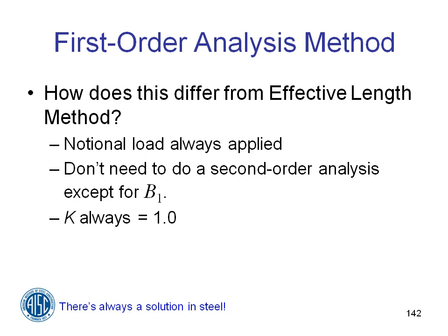How does it differ from the effective length method then? Well, notional loads are always applied, all right? You don't need to do a second order analysis except for B1. And K is always equal to 1. These are significant advantages if this is the method that your structure meets the requirements for.